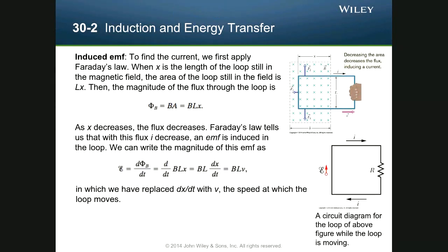First thing we do is we need to use that flux to find the EMF. That's this step here. So we have our flux. We just look at the geometry, and we can get a nice expression for the EMF, right? And then we use Ohm's law, because there will be some resistance in the wire. That's fine.